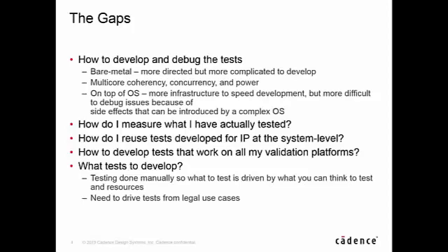So what a lot of people have done, facing those problems, is to move to a pure functional view of saying, okay, I can't write all these tests, so I'm just going to run my operating system and run some application tests on top of it and prove out that my SoC is going to operate under the working conditions that it's going to see in actual application, which is a reasonable approach to at least getting to the point of the use cases that are going to be seen by the SoC.